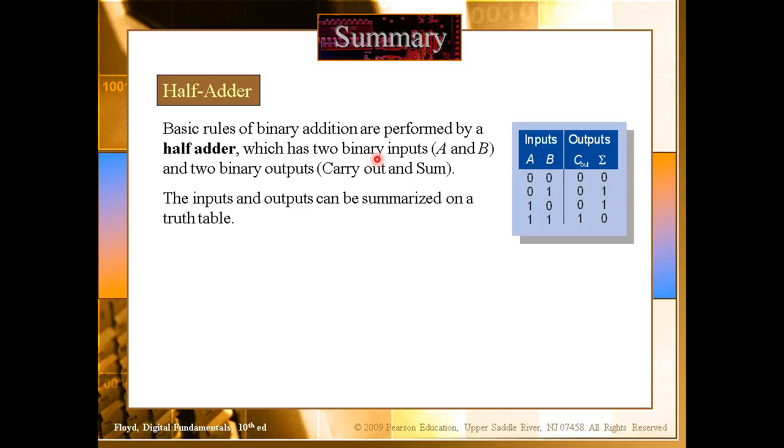If you can recall, or if you can just open that page where you have all the Boolean rules for the binary addition, you probably will be able to notice this. Let's say you have 2 bits, how do you add? When you have 0 plus 0, your sum is what? 0, right? And your carry is also 0. So we actually wrote all of those from the rules, okay? So that means this is exactly what we want to get from the circuit.